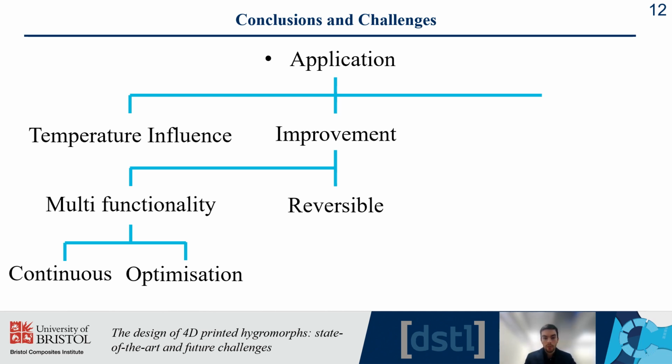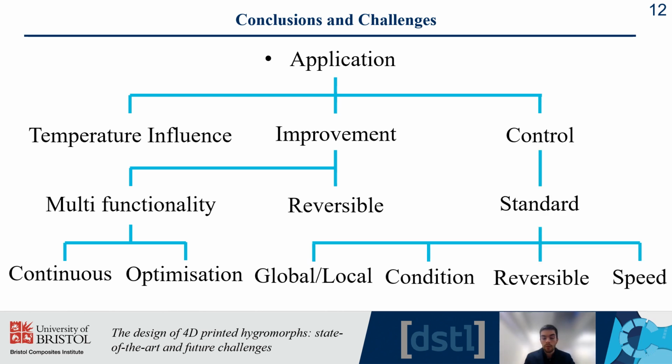And an aspect I have not discussed, but we discuss extensively in the paper, is the optimization of the distribution of material and optimization of parameters for printing, especially the impact of neural networks, which have been used extensively for multi-material structures, and also how we can be inspired by compliance optimization, especially for continuous and short fiber composites definition. This is a big aspect of the research, which we invite you to have a look at if you're interested in the literature review that we've conducted.